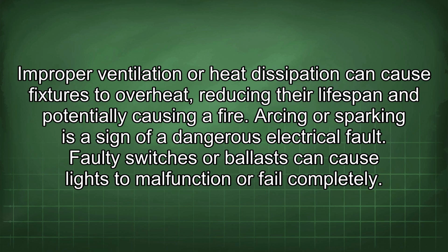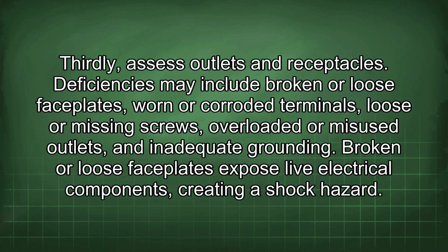Improper ventilation or heat dissipation can cause fixtures to overheat, reducing their lifespan and potentially causing a fire. Arcing or sparking is a sign of a dangerous electrical fault. Faulty switches or ballasts can cause lights to malfunction or fail completely. Thirdly, assess outlets and receptacles.